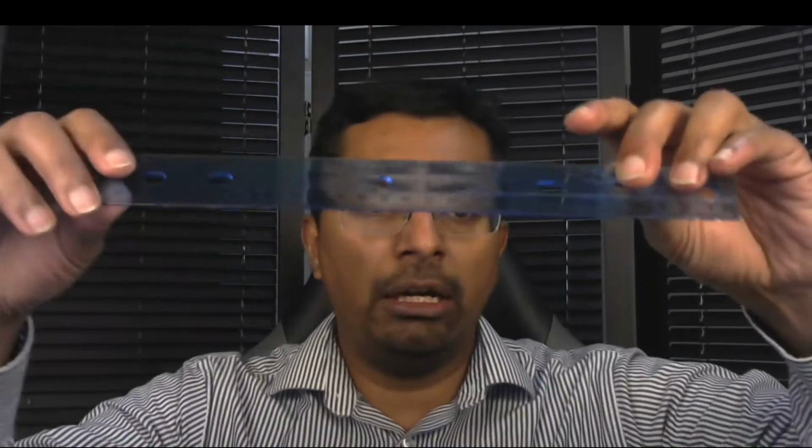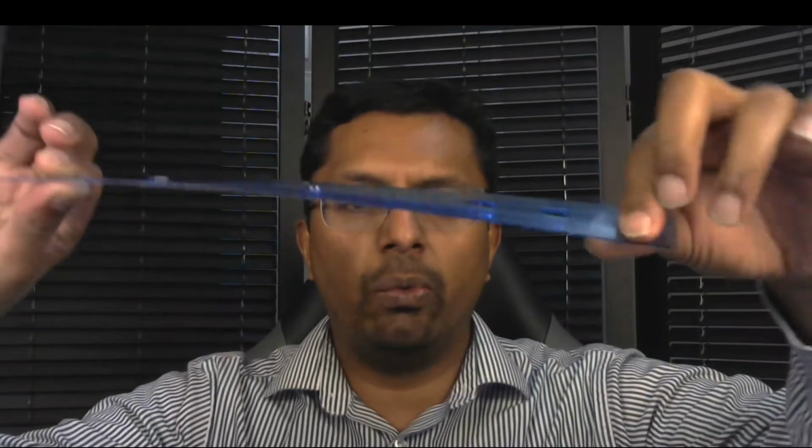So you have a size, which is how long a part is, and then you also have a shape, right? So instead of this ruler being straight, you could have it twist one way or the other. That affects the shape. Similarly, if you think about designing a cylinder, you can have the cylinder warp all over the place. The cross section may not actually be circular. So all of that are the geometric features of that particular part.